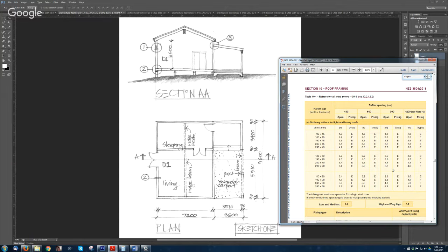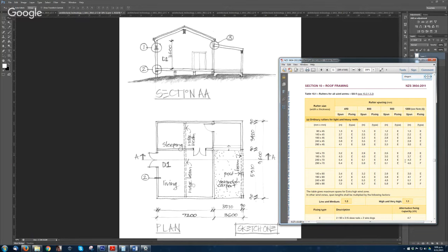For this question, you don't need to find the loaded dimension. Alana's asking about the loaded dimension. For this structure, remember, you don't need it. I can explain the loaded dimension, but it'll be easier when there's a question where you need to find it, later on. The veranda beam one is a good one to explain it with. For now, for just the rafter sizing, you only need to know the spacing and then the span. So the span is 3.6. That's the only thing you need to know.